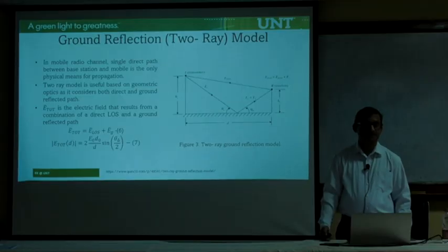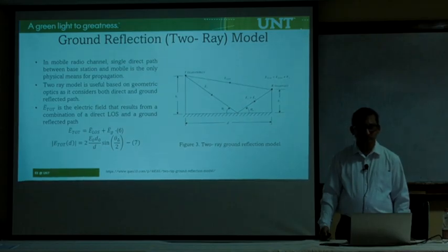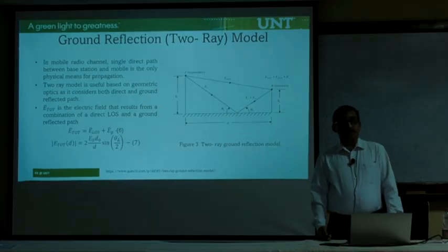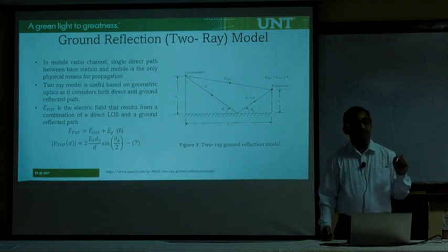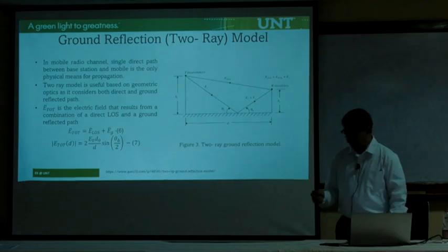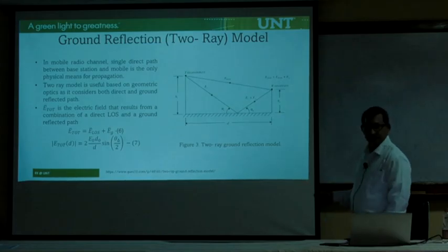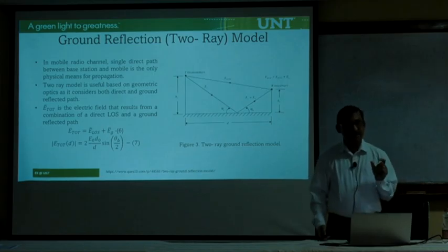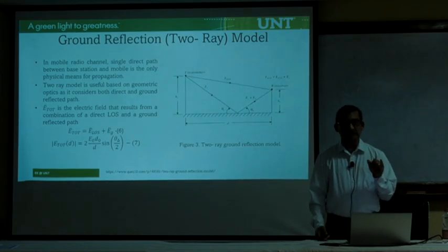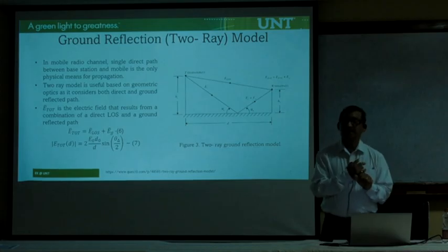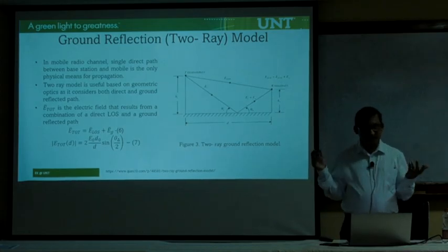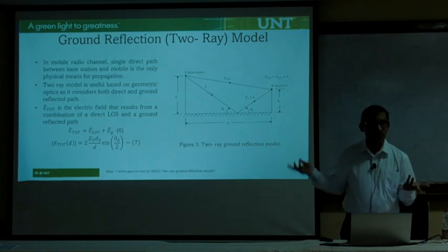Right, exactly. So how do we reduce the signal from the overlapping or other message signal or same signal? In fact, really speaking, you cannot reduce anything. You can't change the physical phenomena. But first of all, you have to estimate how long you are going to get these signals. For example, here you're getting one copy, then this is another copy, and then you get more and more copies. So there are some metrics we're going to look at. Delay spread is one that captures how long you're going to get these copies. Okay, that's number one. Number two is, you cannot change the physics. You cannot eliminate them, because you cannot remove the buildings. It's not in our control.